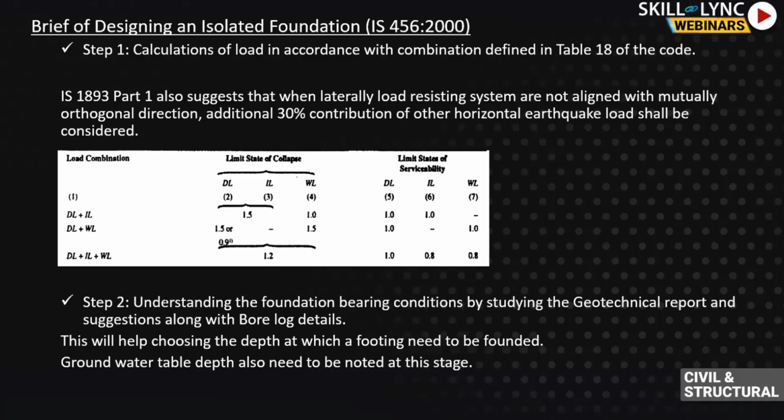Once that is decided, the depth of footing and bearing capacity of that location, one can proceed to the next thing, which is basically understanding the load that is coming on top of the foundation and the bearing area requirement.